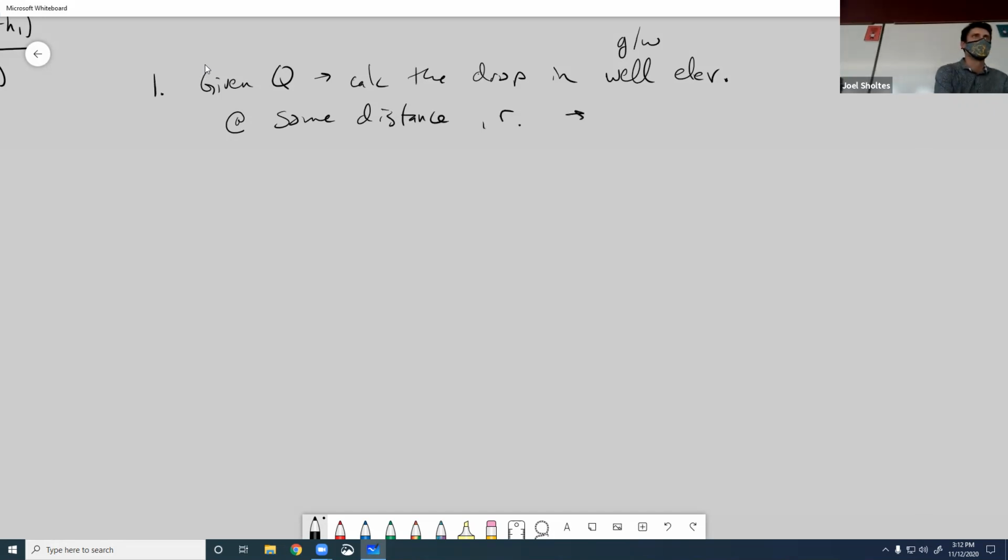So this is like a drawdown, you know, how much am I going to impact my neighbor's well? Or am I going to create a reverse gradient so that all of a sudden water is starting to flow from an area where it didn't before? Because you can reverse directions of groundwater flow. We talked about that example on Tuesday where you could potentially be drawing water from a surface source that you didn't want to go into your well.